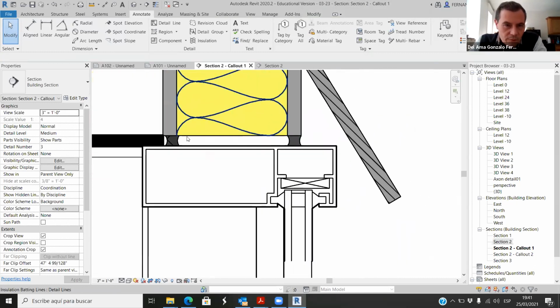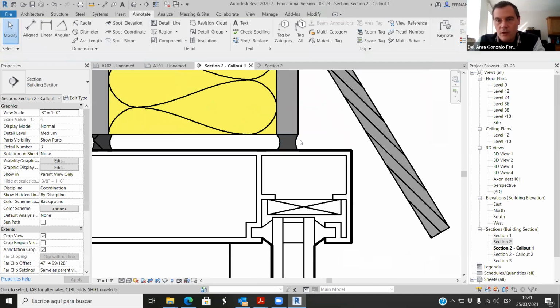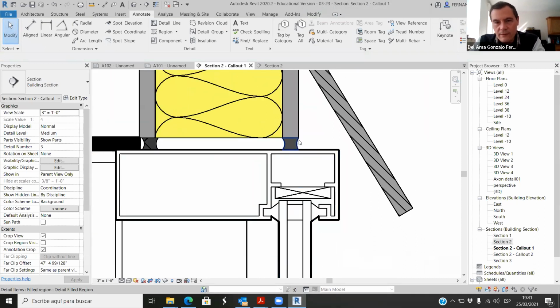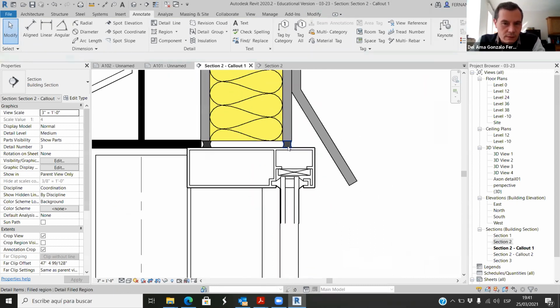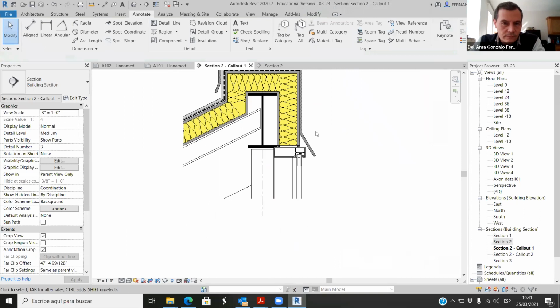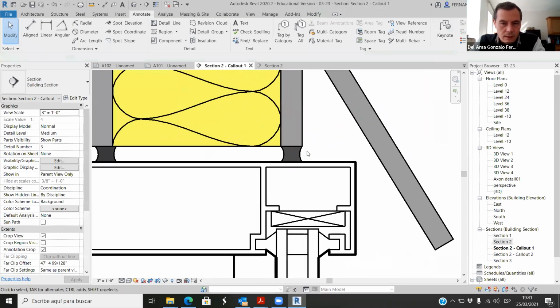This is important. If we have a double sealant, it's much better than just a single one. Does it last forever? Not at all. In 5 to 10 years, depending on the weather and the temperature, we have to replace all these. These kinds of details need maintenance.